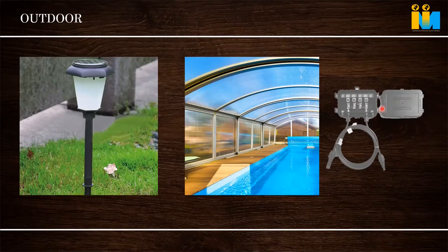Okay, so how do the raw material people test weatherability? They cannot keep the raw material for 25 years and validate and come to the customer and tell, okay, this passes. So weatherability equipment is there, which can create this in the lab itself. It's accelerated weathering. Normally atmosphere is 35, 40 degrees. Accelerated weathering means within a short time, that much amount of light energy will be given to the part, and cyclically it will be done.